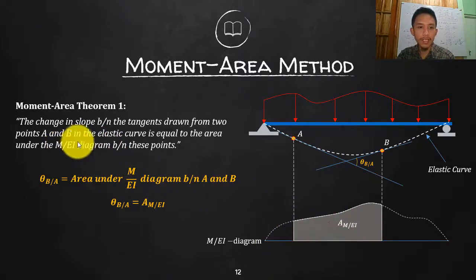If we say E, that is talking about the strength of the type of material. If that is steel, the E is different from the E of concrete. So E defines the type of material. However, your I is with respect to the shape. Even if both are steel, if the shape of one is I and the other is square, their strengths are different even if they are the same material. That is described by your moment of inertia, which holds the strength with respect to the shape or the orientation.